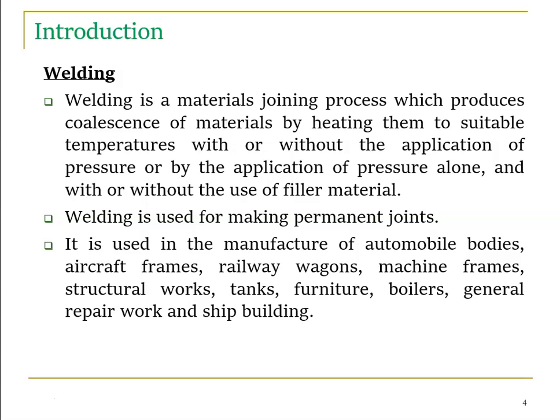Filler material is a material used to fill the gap between two metals. If you join two metals, there may be some gap, and that gap needs to be filled with the help of filler material. So, with or without the use of filler material. This is the definition of welding: a material joining process which produces coalescence of materials by heating them to a suitable temperature, with or without the application of pressure, or by the application of pressure alone, and with or without the use of filler material.